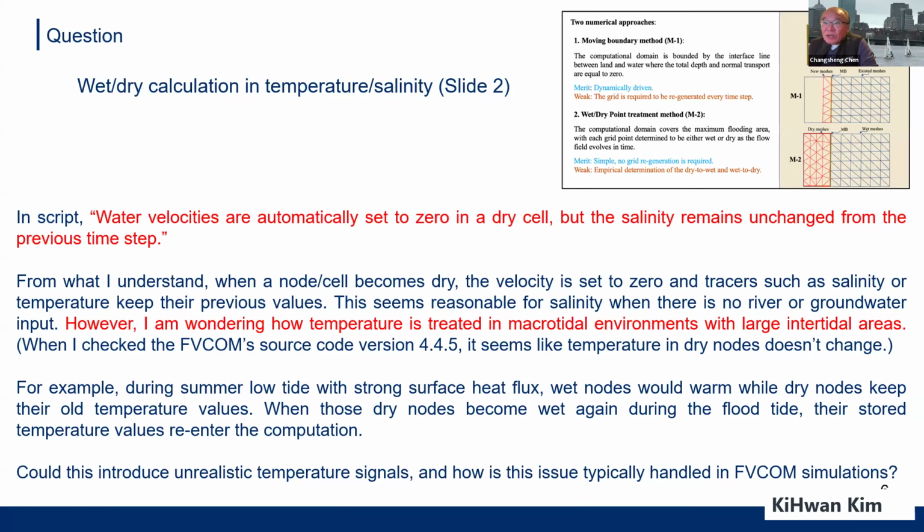To be honest, most of our wet-dry model is for coastal inundation. That's the reason we developed the wet-dry model. We know that. That's why, with a 3D model, we have to consider temperature and salinity, but with the assumption that everything in there is probably not true. Only the water transport is probably true, because we validated it in my paper, showing the water level and water flux compared with observation are correct, including speed, timing, and maximum sea level. But we never compared temperature and salinity, because we only put them there to make the model stable.